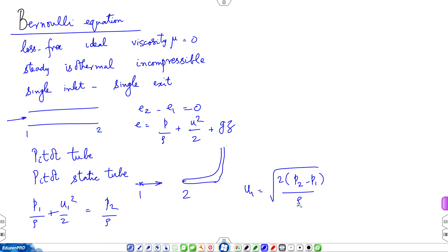Now, this solid rod has brought the fluid particles to rest. Now, if you can measure P2 somehow relative to P1, for that you can think of a very small diameter hole which serves as a tap. A tap is a very small hole through which fluid pressure is communicated.